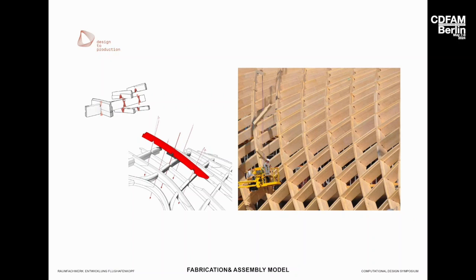And the assembly sectors, setting them up and defining those assembly sectors, is very much dependent on the systemic structural behavior. So you cannot just divide the clusters as you please, but you have to consider local conditions, transportation constraints, and structural behavior of the grid shell itself.